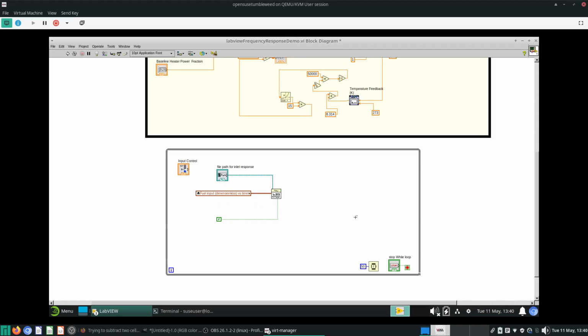Let me show you what happens when you just leave this part blank, or at least turn it to false, because by default I think it's false. Let's see what happens. Then you say replace existing waveform. Then at every time step, it will ask you whether you want to replace, which is something I don't want. So you have to turn this to true to have it run in the while loop, and turn the headers off.